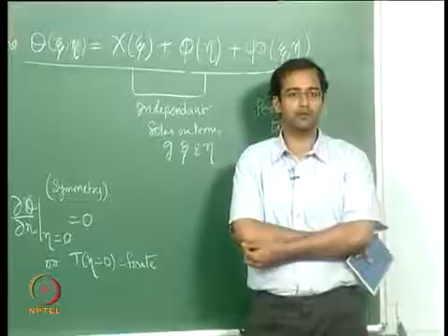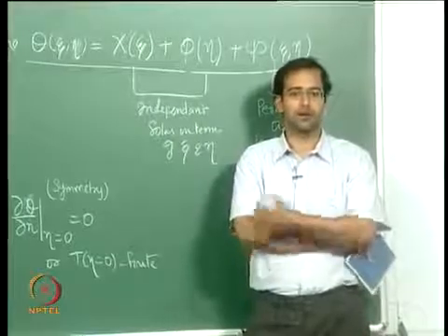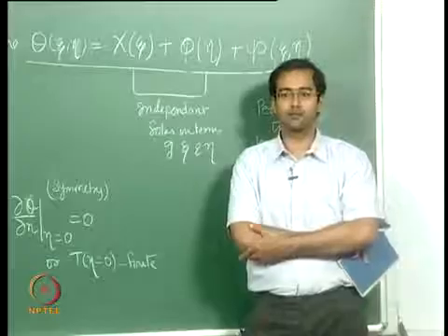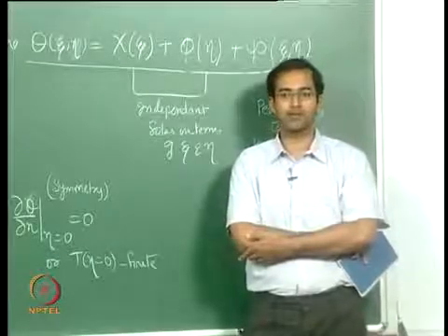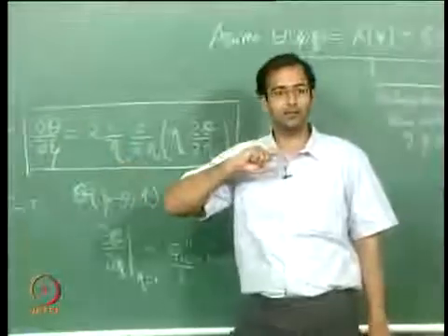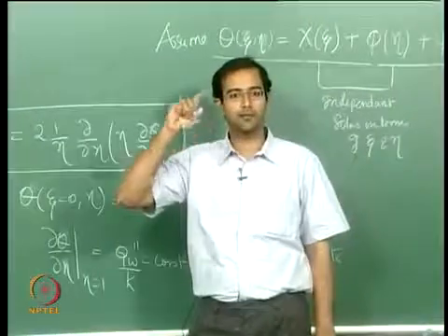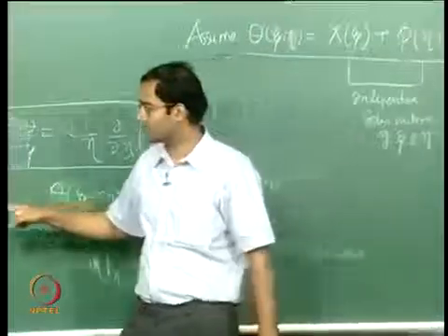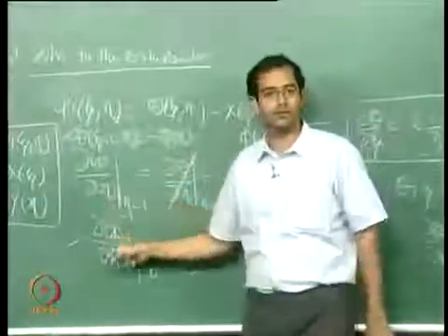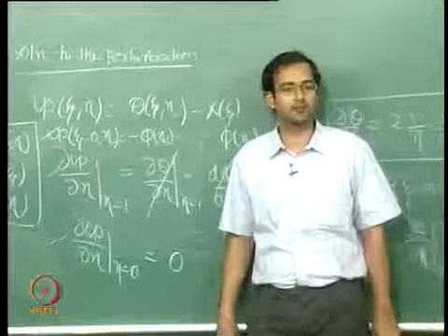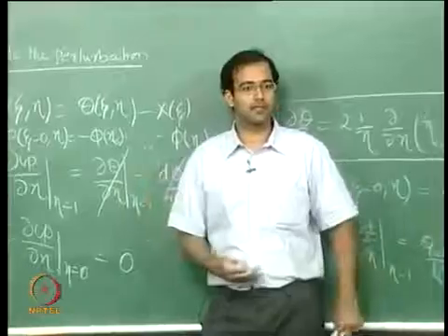It will be a Bessel equation, and you already know the solution to Bessel equations. You have to just combine the Bessel solutions, and the only difference between this and the constant wall temperature case is that there the temperature was 0 at r equal to r naught. Here you have both gradient 0 boundary conditions. Okay. So this is the difference, and after that the solution is straightforward.